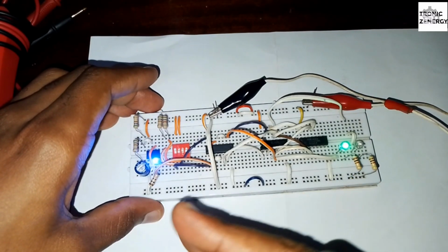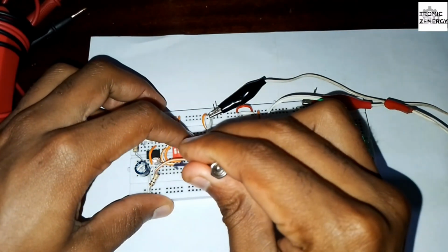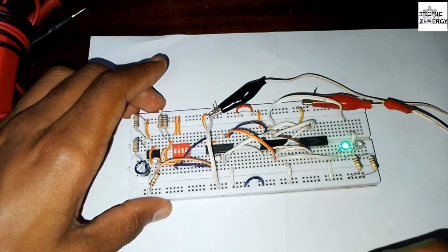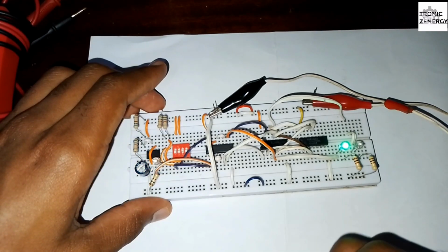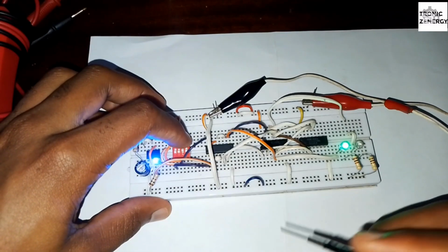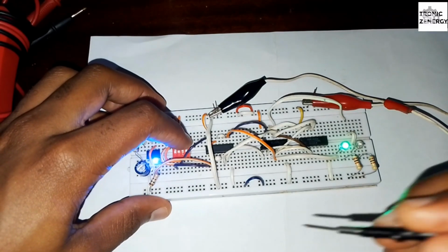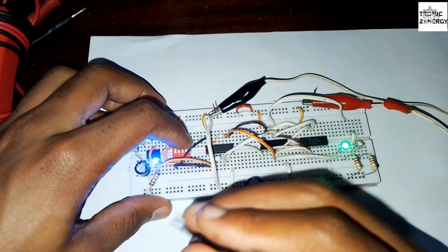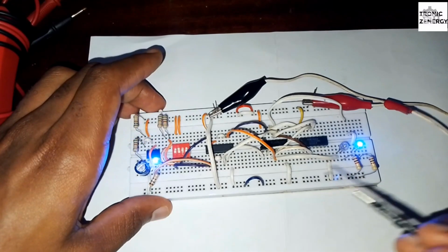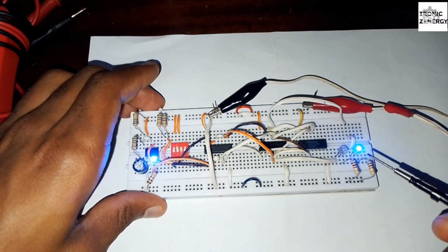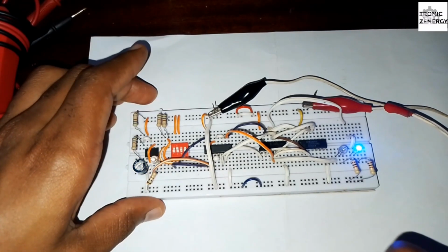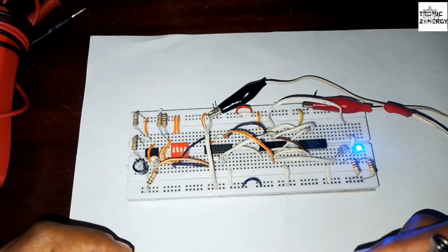So the green LED shows us that we have fed data to our circuit, and nothing happens even if I turn the switch off. The circuit still remains at that state, because of how I explained it in the simulation, if you understood it. Yes, so the only way to reverse this or to change the state is to press the K switch like that. When it aligns with the clock, it gives a 1 output at the Q bar, meaning that we have reset our data. So that's basically how the JK flip-flop works.